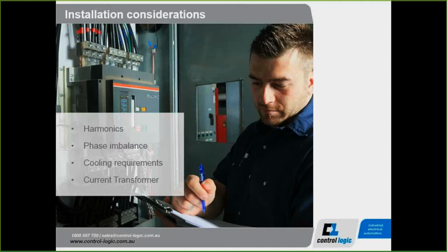So, if your total harmonic voltage distortion exceeds 8% on your network, it's not recommended installing a power factor correction unit. Instead, you need to fix up the problem that's causing these harmonics. It could be you might have to install an active harmonic filter, or if the harmonics are confined just to a couple of pieces of equipment, say a couple of large variable speed drives, you might look at other options like installing passive filters specifically for those devices.